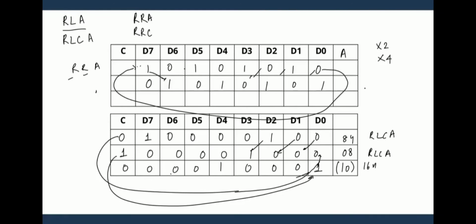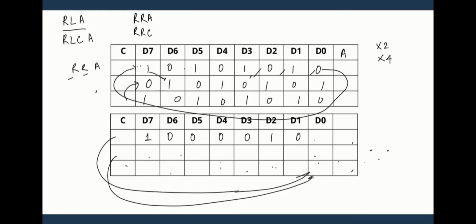It moves right 1 bit. Then what about the case with RR? If you are rotating again, this D0 1 will come to the D7th bit, and D7 becomes D6, that is 10 10 10 10. No carry flag is affected or changed.